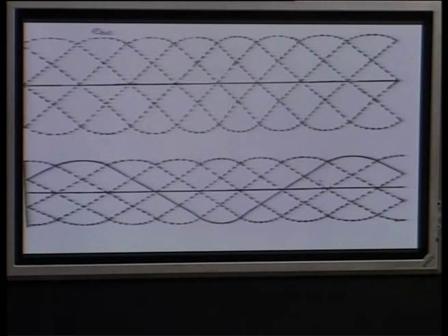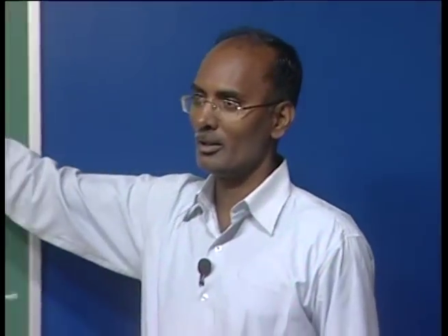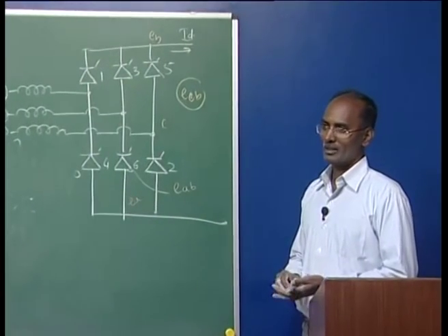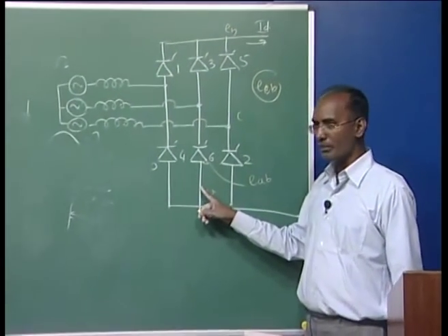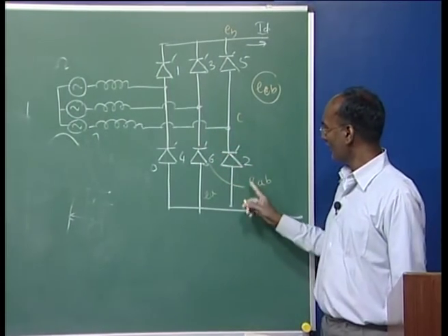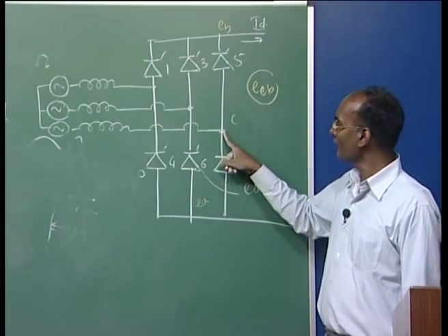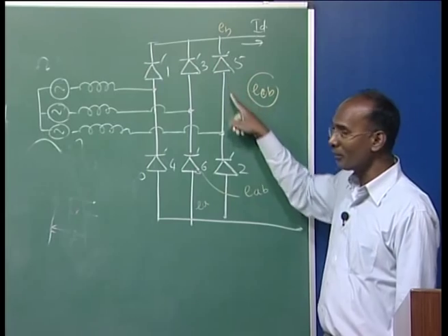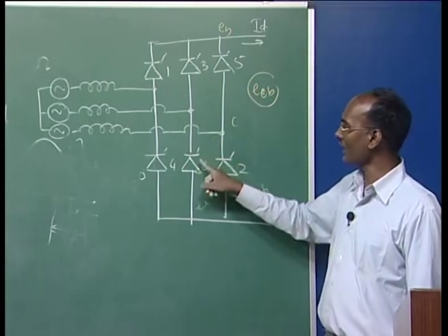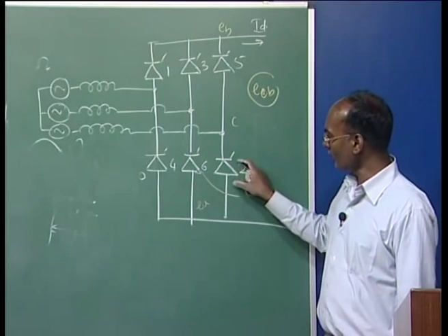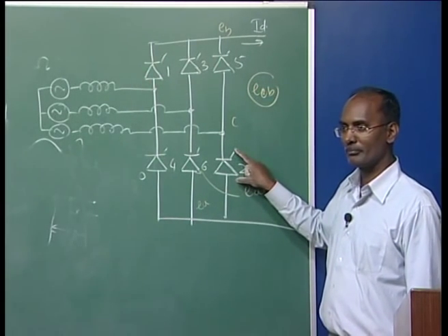In my lecture I always took EBA as the starting voltage, because this was the commutation voltage of valve 3, but this time I have changed, and now we will see what will be the commutation voltage of this valve. You can see it is BC, B is on the positive side and on the other side it is C. Here, C is involved, so it may be the possibility of this limb. Now, what will be the commutation voltage of this valve?